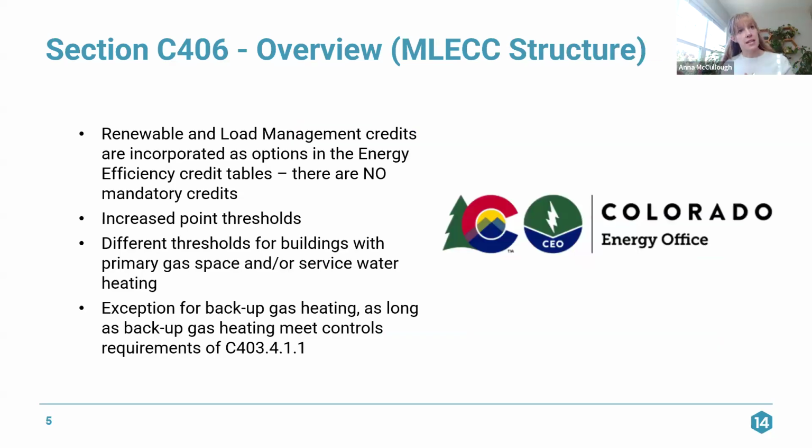So now CEO and the code board have amended the 2024 IECC to hopefully streamline things a little bit. The renewable and load management credits that we talked about under the 2024 IECC that are mandatory are now no longer mandatory, and they are combined in with the additional energy efficiency credits. So all of the credits are in one table, and you're not having to jump between sections to figure out which credits come from which table and how they interact together.